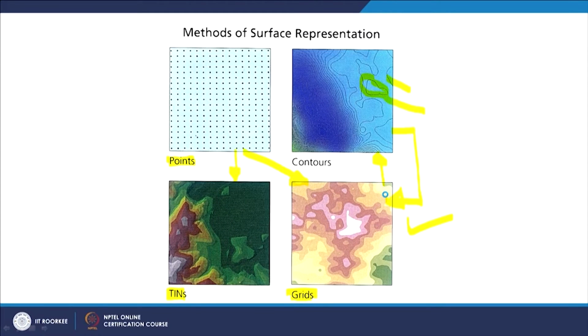But suppose the software you are using is not capable of doing that, then there is a very simple method: you can convert this polyline first into points. Such tools are always available, and then using points you can create a surface. These software tools you have to use judiciously and very intelligently. Basic tools are there, only you have to find the best way to create a surface.